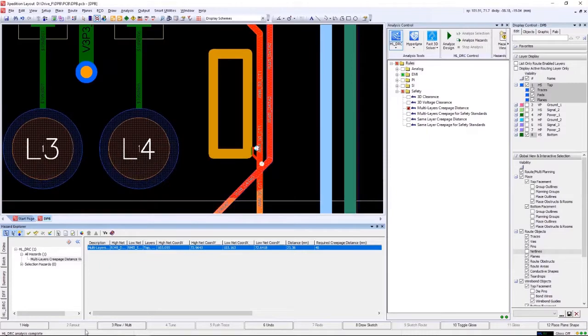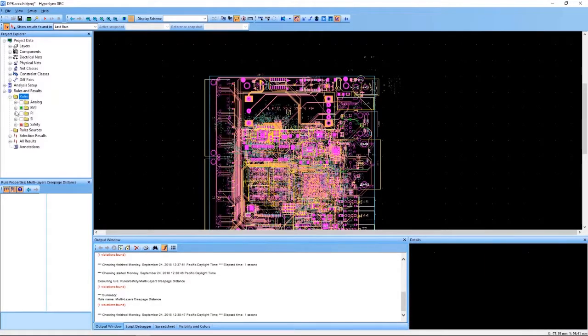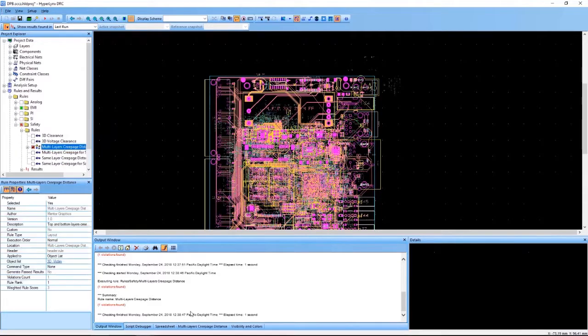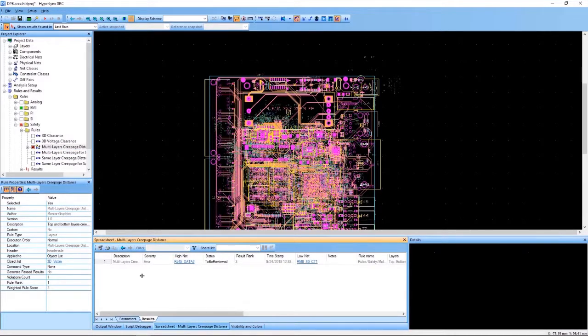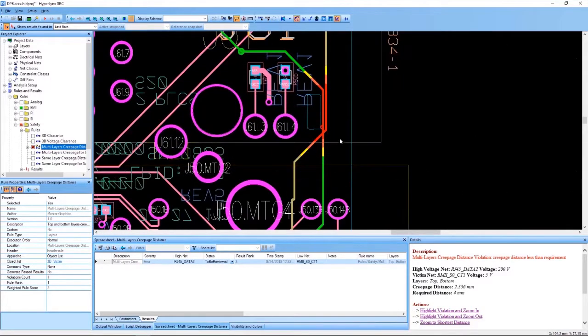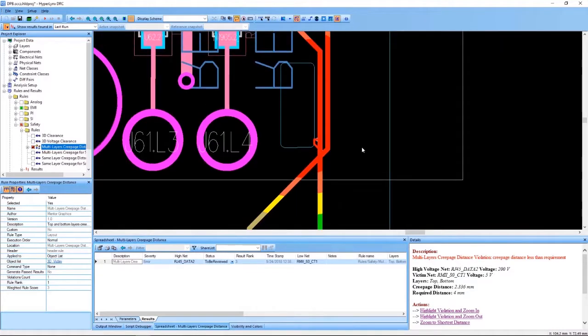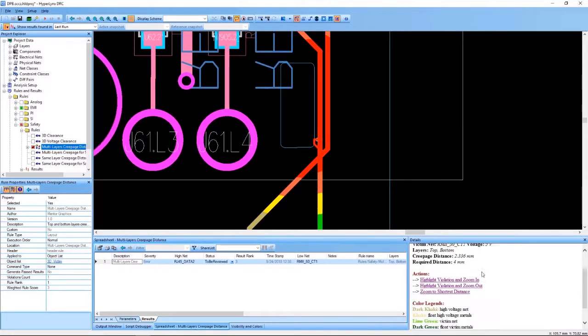And since we're using Expedition, we actually can make these changes immediately. I can move that net immediately. I can choose to fix this problem right in my layout stage. And here, I just want to show HyperLynx DRC standalone, how it also reports the same violation if you're using the standalone tool versus using it inside of Expedition.